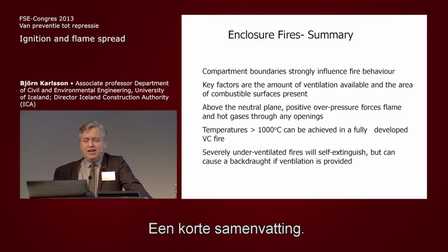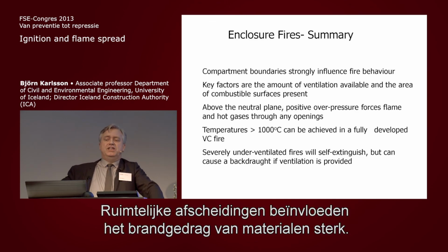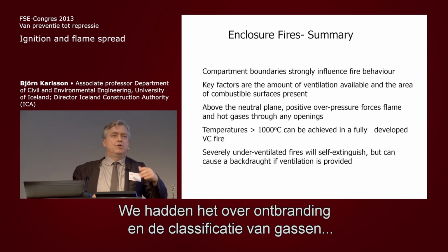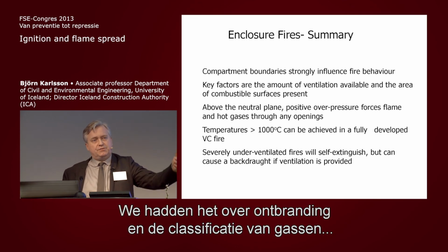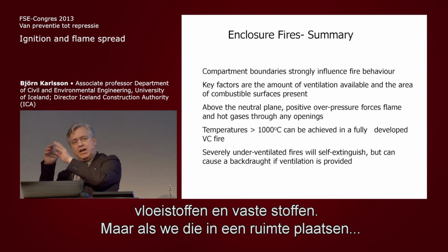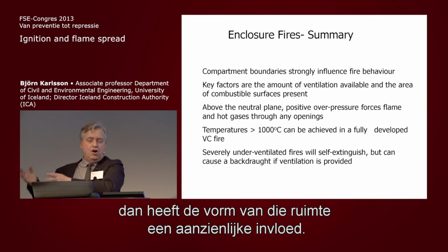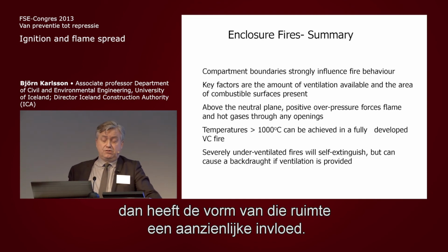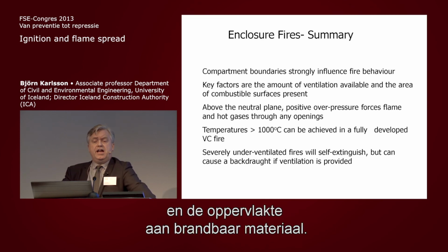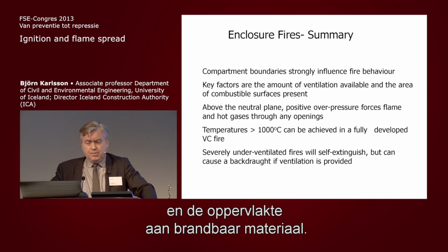So a little summary. Compartment boundaries strongly influence the fire behavior of the material. So we've been talking about ignition and how we classify gases, how we classify liquids, how we classify solids. But when we put these into a room, the geometry of the room is going to have a considerable effect. And the key factors are the amount of ventilation available and the area of combustible surface.